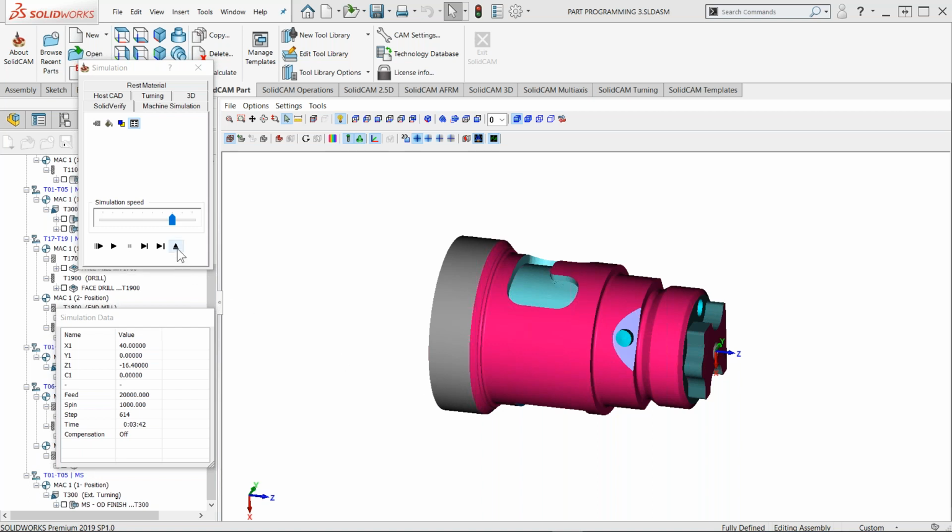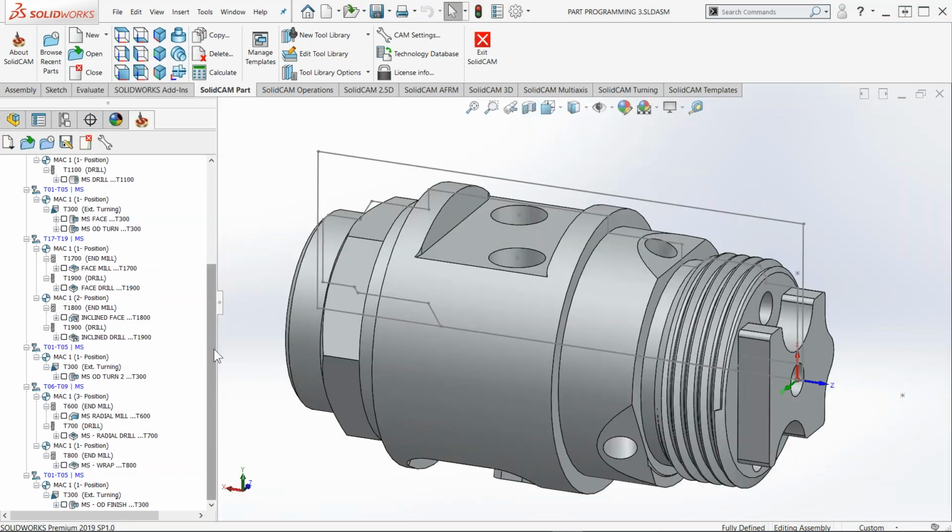But before doing a cutoff, we need to bring the machine into a state which is necessary before making a cutoff operation. In Swiss type machines, there are basically two things that you have to do. We need to select the cutoff tool and preposition the part. And the second MCO will be bringing the back spindle to the clamp position where it will hold, and after that we'll have the cutoff operation. So let's see how to do that.